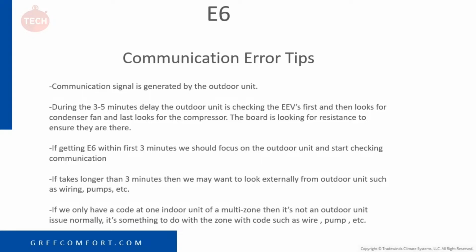If it takes longer than 3 minutes, then we may want to look externally from the outdoor, such as wiring, pumps, etc., which we'll get into. And if we have a code at one indoor on a multi-zone system, it's something to do with that separate head. If we have a multi-zone with a code on all, say, 3 heads, and it's a 3-zone system, then we know we probably have an outdoor issue. If we only have it on 1 head of the 3 zones, then we want to focus on that 1 head, the wiring to that head, or the pump.